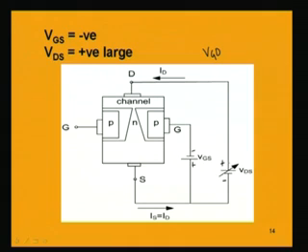So, if we go on increasing VDS too much, then the depletion layer width will be increasing and increasing, and the N channel will be having a modulation in its width. It will be tapering towards the drain side. That is, the width will be maximum at the source side and it will be tapering or narrowing down towards the drain side, because at the drain side the reverse biasing potential for this PN is maximum. So, this is due to the increment in the VDS too much.